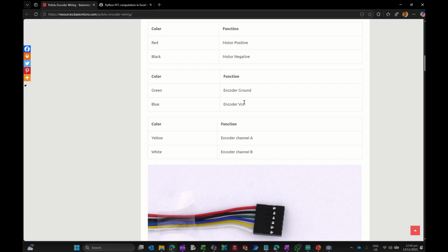These absolutely have to be according to what is called out here. You cannot do bidirectional because the power is coming in to the encoder VCC from the ESP32. And then channel A provides you the reference to get your speed, right? So this is essentially the setup.